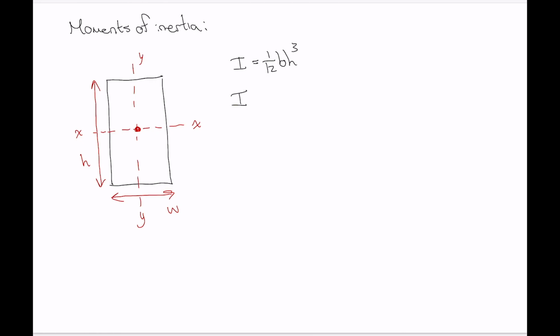So if we want the moment of inertia about the x-x axis, here we're taking 1/12. The base is W, and our height is h cubed.